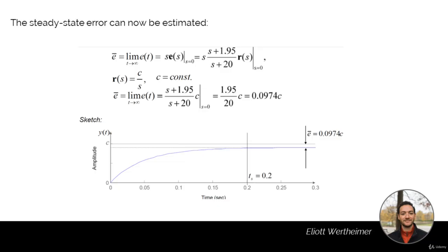So as this error gets closer to zero, the proportional control reacts less and less, simply because it scales that error by a constant value, your proportional gain. Imagine that the smaller that error becomes, the less the proportional control is going to act, until the error is so small that the control does not act anymore, and so you keep that error forever.